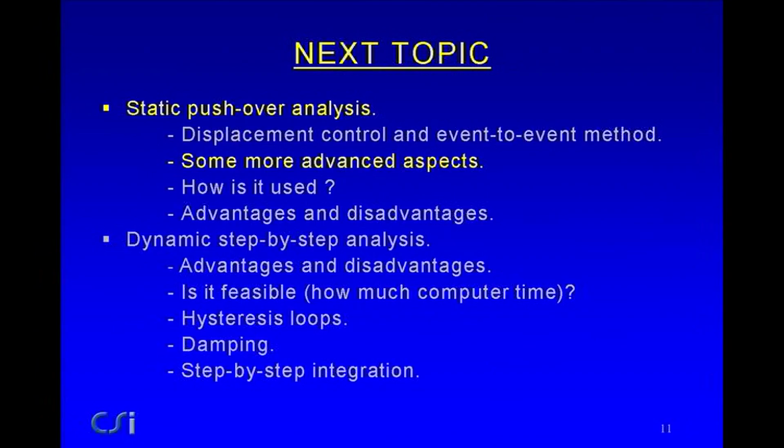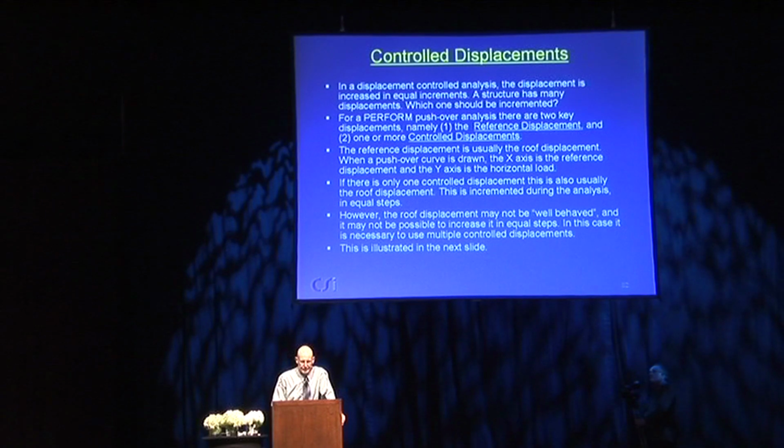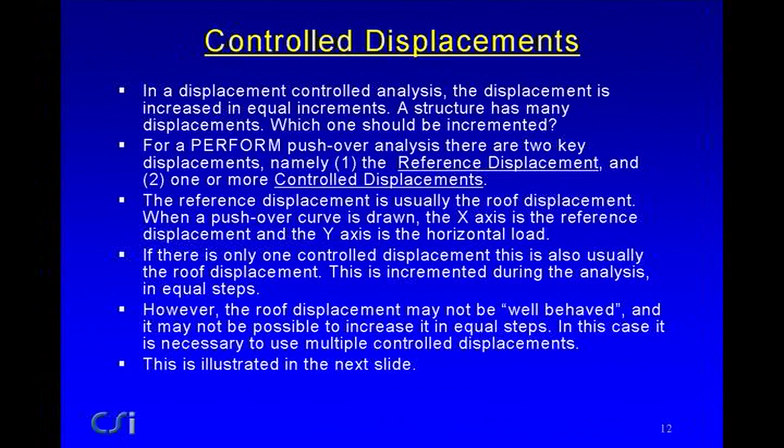So the next topic, that was just very briefly on the basic method. A few more advanced aspects. This is something that you do need to consider, and this is controlled displacements. As I showed, in a displacement-controlled analysis, you increase the displacement in equal increments. And the thing is, the structure has lots of different displacements, thousands of different displacements. So which one do you want to increment? You can choose any one of those thousand.